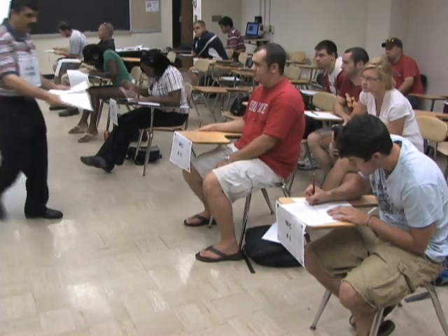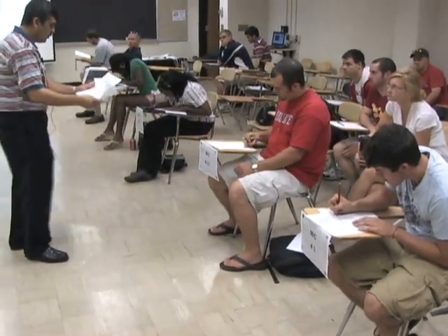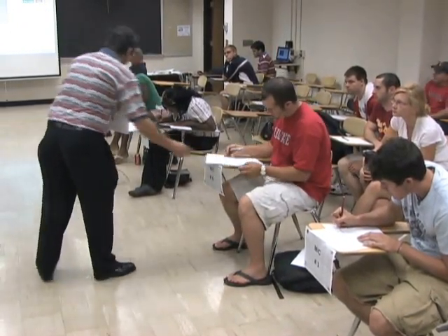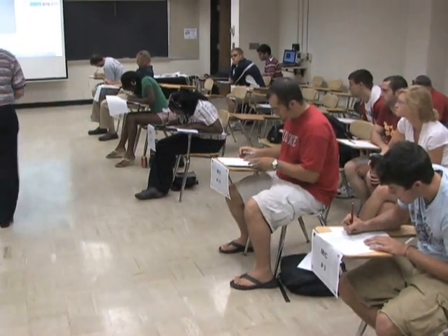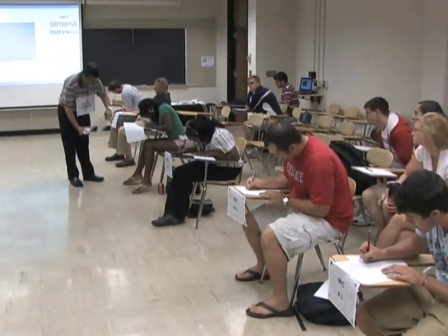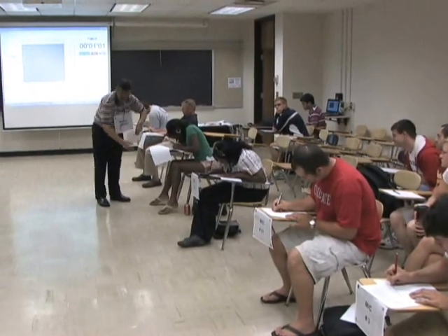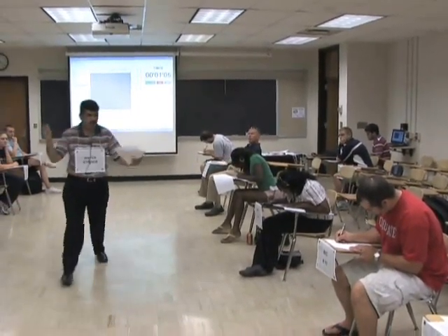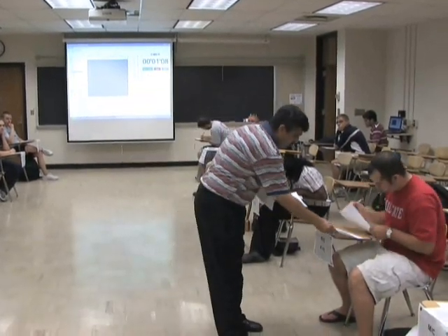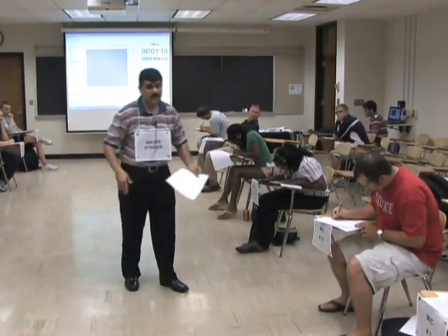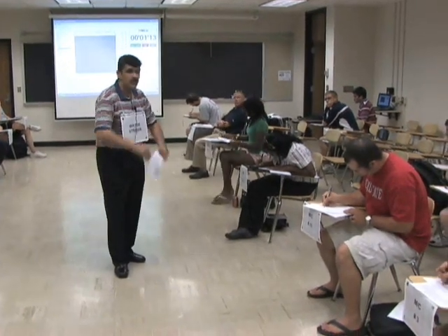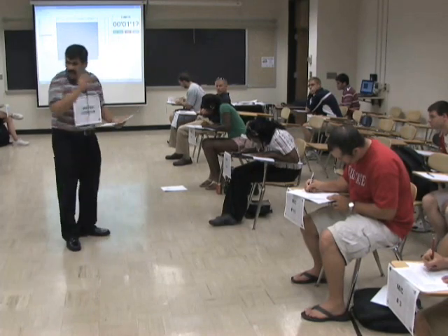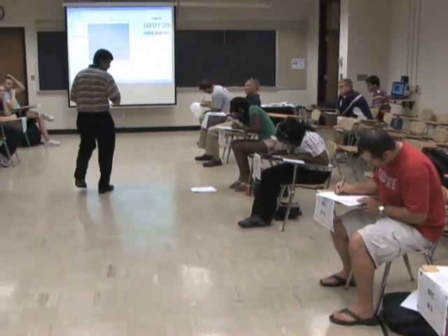Of course, it won't be this uncoordinated in a real factory. They'll at least know where they're going. But do you see what I'm doing? I'm just putting a first in, first out sequence on the work. I couldn't care less in what order I'm putting the work in front of a person. And that machine operator also doesn't ask me, what are the due dates? Are there any priorities you wish me to execute? Just give me the work, I'll just do whatever you give me. So when people are moving in big containers and they just drop in a random sequence, the person just says, what is the easiest to reach and get? And from there start the evils of the badly designed factory.